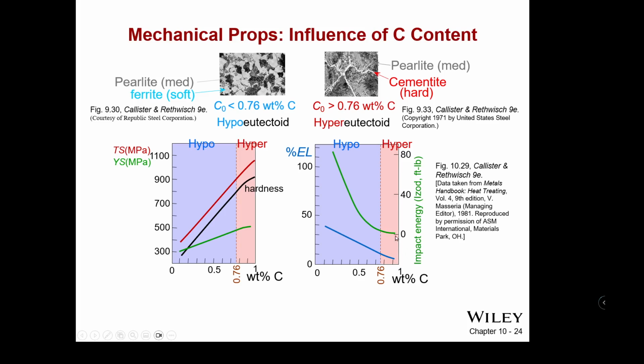Hypereutectoid, especially, is very brittle, very low in terms of flexibility, very low impact energy, very hard materials, very brittle, can't absorb a lot of energy. Highly ductile materials absorb a lot of energy, deforming the metal. So this is why in crash structures we want ductile metal. In cutting edges we want brittle metal, because those tend to give us the hardness properties that we need to do the cutting job, where we don't want flexibility. It's very important all of those things go together.